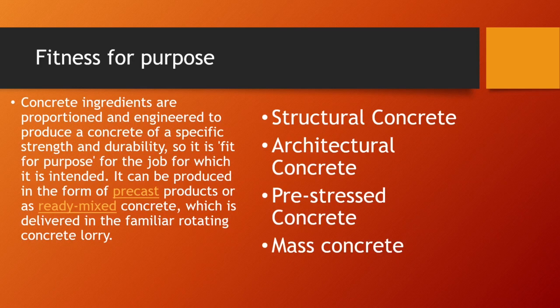Then we've got the C50, which is far stronger, far tougher. Typically the college would be built on C50, hospitals, bridges, typical infrastructure. There's also architectural concrete, which is effectively concrete that potentially has a purpose. It generally does. It has a purpose in a structural sense, it's holding something up or retaining something, for instance. But it also looks good. Okay, so it's serving two purposes.